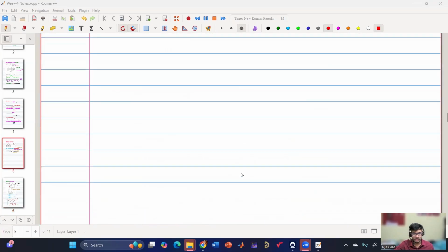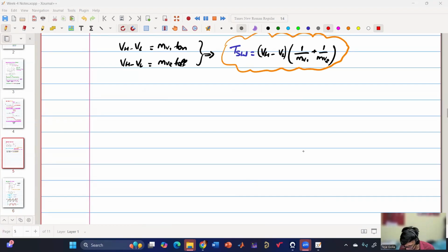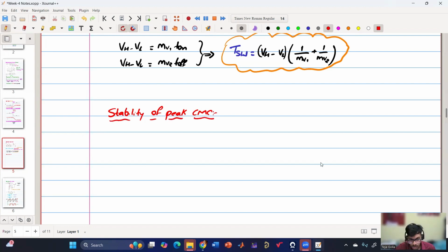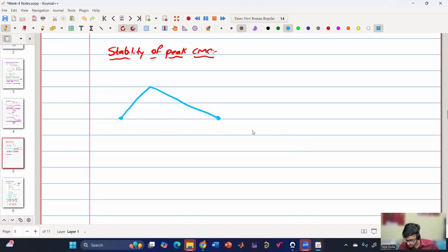It all comes from the stability aspect. What happens is we have peak current mode control, something like this, right? And say the peak reference is fixed. Now what we are doing is perturbing it, say up or below.